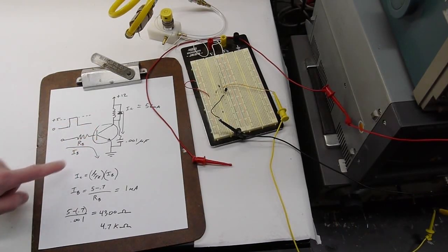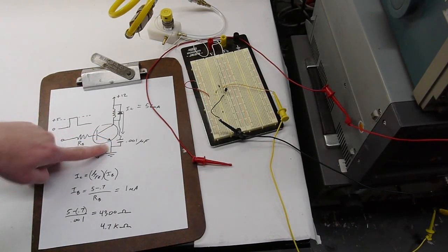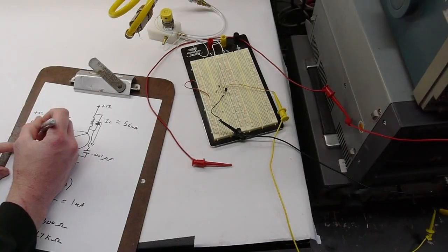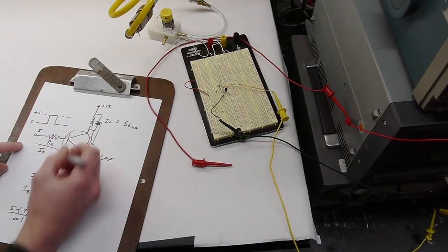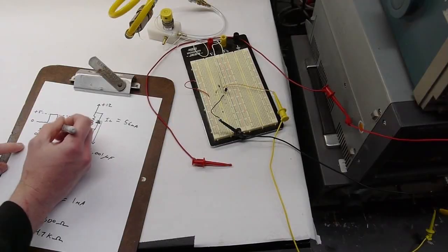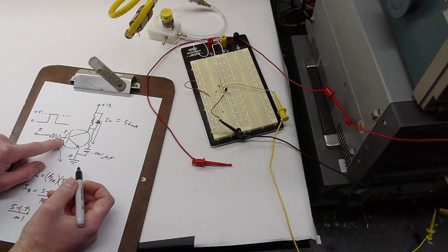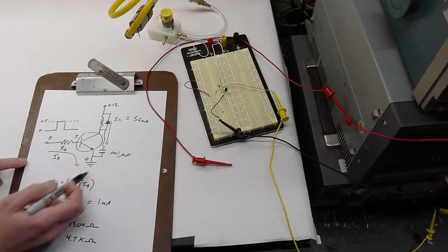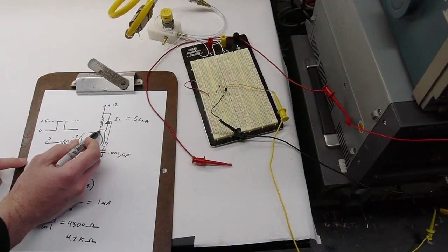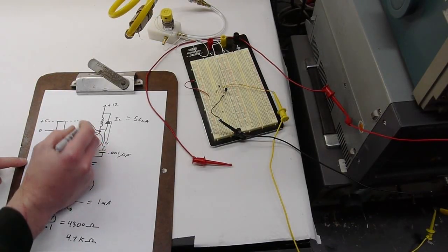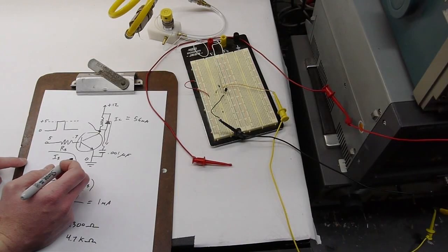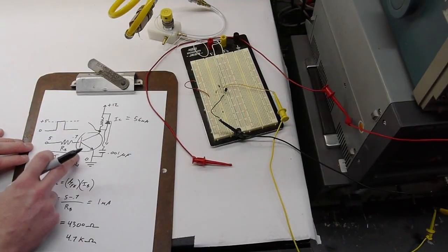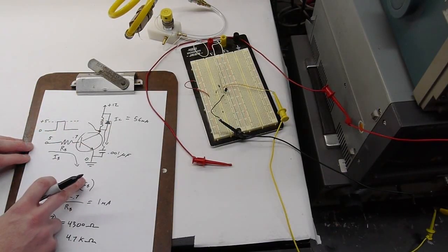Also, there's going to be a voltage drop across here. So I said that there's a 0.7 voltage drop here. So if we measure all these voltages, we've got 5 volts here, we got 0 volts here, we've got 0.7 volts here. That's 5 minus 0.7 over RB across this resistor gives the current flow through here. But what's the voltage right here? This is actually pretty interesting. This voltage could be close to 0, or it could be about 0.1 or 0.2 volts, depending on the transistor and how much current is flowing through it.